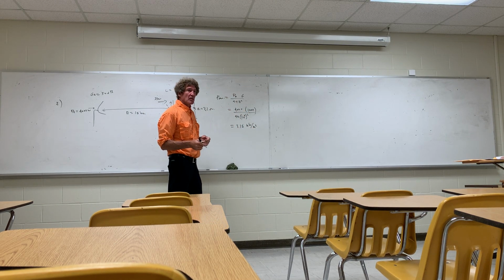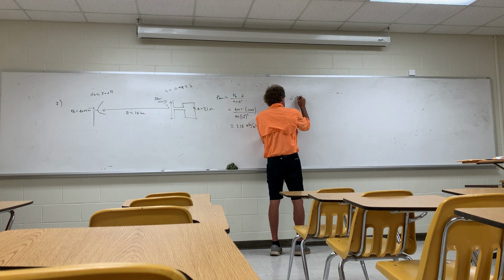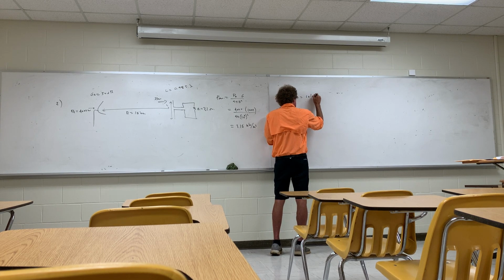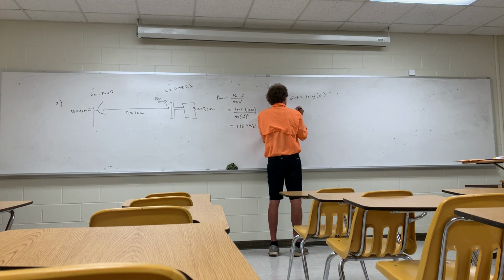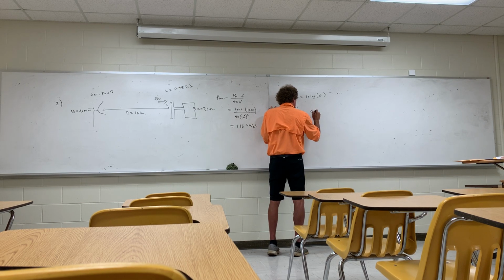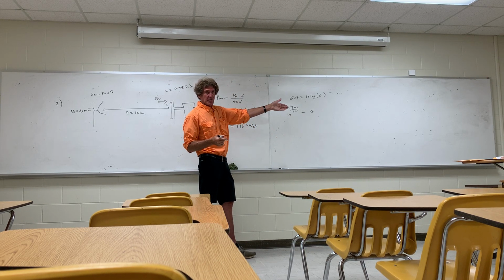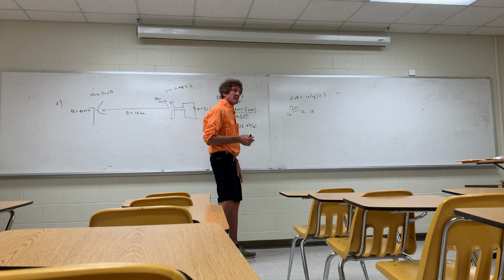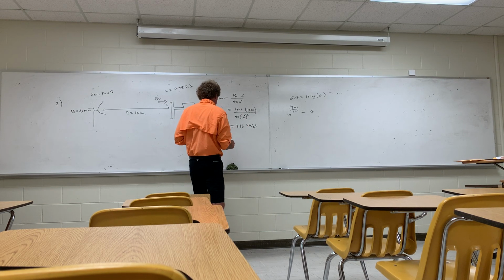Can you do the 1,000 conversion for the gain? Yeah, it's just a standard dB thing. When you have gain in dB, that's 10 times the log of the linear gain. You need linear gain here. So you take this gain, 30, divide by 10, then take 10 to that power, that would be 1,000. That's gain. By the way, there were 2 problems with gain on it. And I gave you several where you had gain in dB, if you look at the homework. Matter of fact, I don't know how many I gave you, but that's a common way for this to work. So that's the average power density.